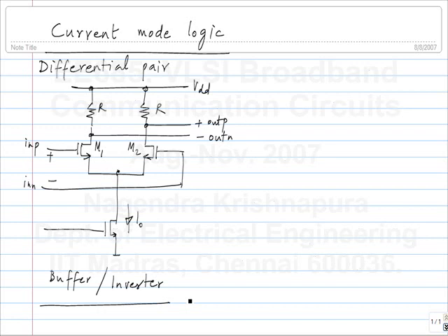And one of the first things we do when we have a logic gate, for instance, when you have the CMOS inverter, is to draw the input-output characteristics. Okay. So here, this is the input, and the output is V out P minus V out M. What does this characteristic look like? I just want the output versus input. What does it look like? Straight line.